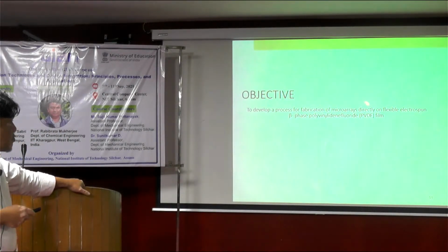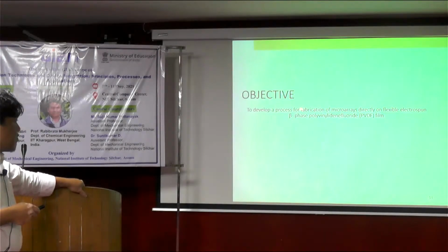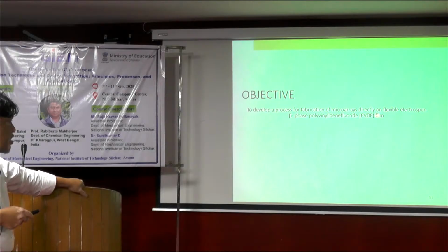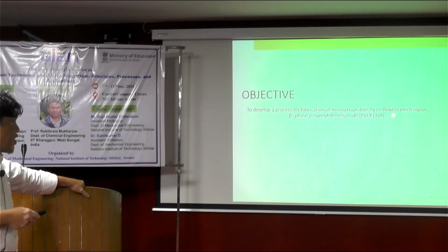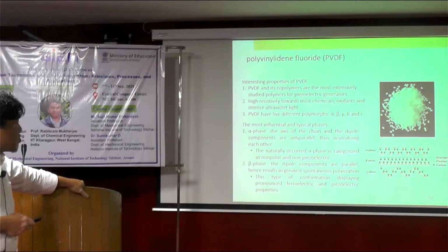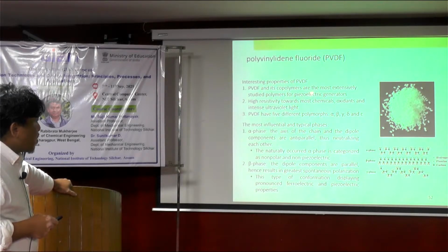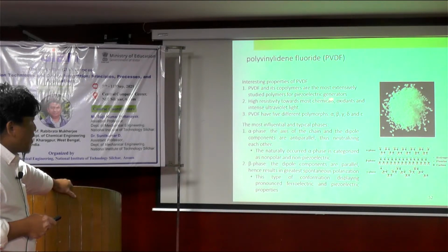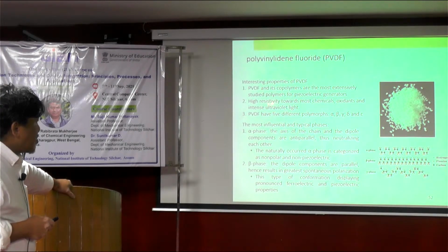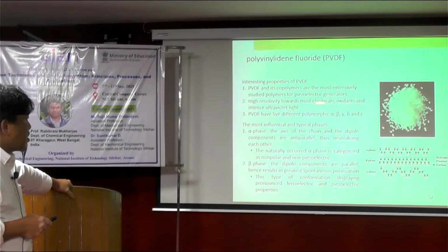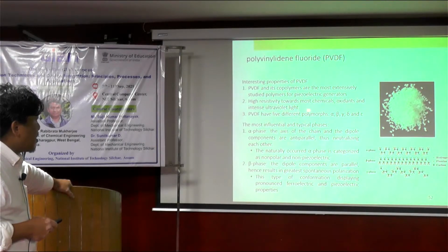So here, the objective of this design is to develop a process for fabrication of a microarray directly on flexible electrospun beta phase PVDF film. This is a PVDF material. It's a copolymer, the most extensively studied polymer for piezoelectricity, with high resistivity towards most chemicals, oxidants, and intense ultraviolet light.